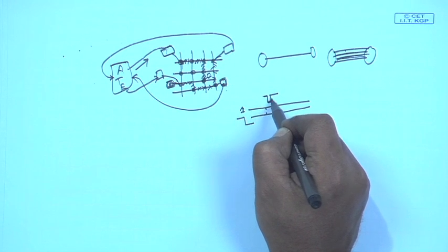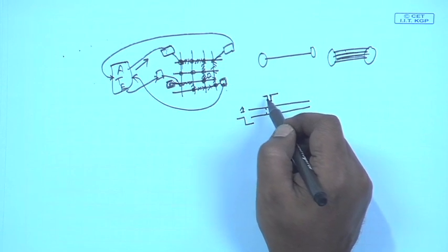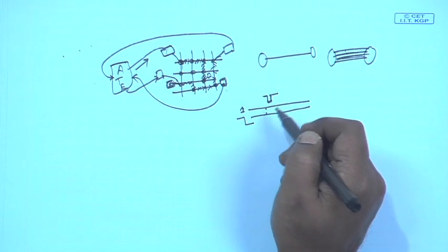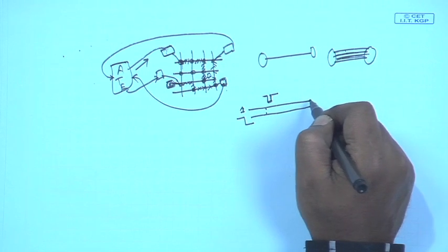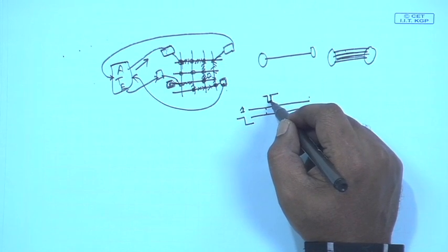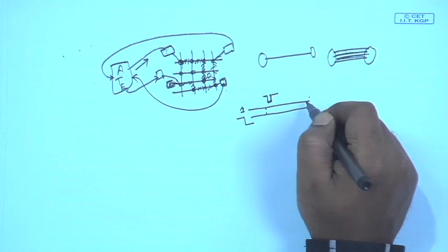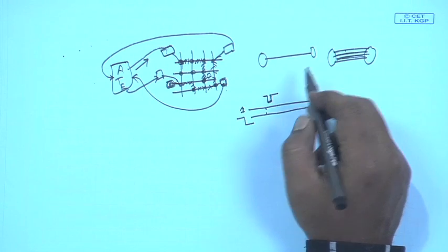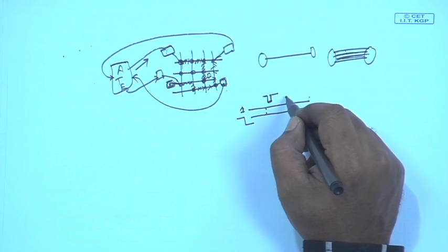Now, if this voltage level drops significantly, then there is a possibility that at the receiving end we are sampling the line at this time, as a result we get a wrong logic value read, or if there is a positive glitch.